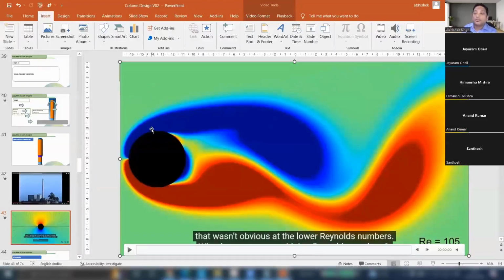Okay. So now you'll also understand that when there's a wind-induced vibration, the direction of the vibration is not in the direction of wind. It is perpendicular to the wind. That is really interesting. If wind is happening in this direction, the wind-induced vibration will happen perpendicular to it.